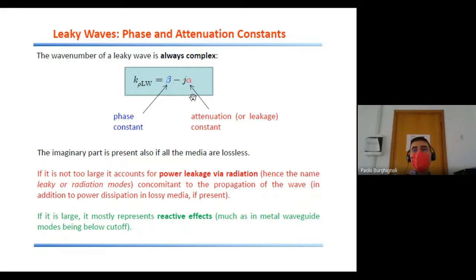However, if the imaginary part is too large, then there is also a second physical mechanism, the accumulation of reactive energy. In that case, the occurrence of an imaginary part is closer to the evanescent character of a mode below cutoff.